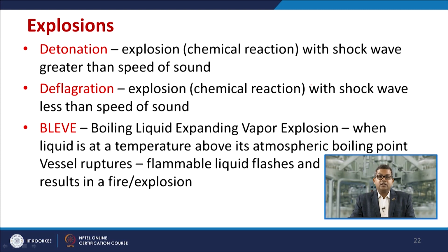Detonation: an explosion, a chemical reaction with a shock wave greater than the speed of sound. This is extremely dangerous, because sometimes the shock wave generated due to the explosion may match the natural frequency of an object, and that object may be destroyed or may collapse. So detonation is extremely important. Then deflagration: an explosion or chemical reaction with a shock wave less than the speed of sound.